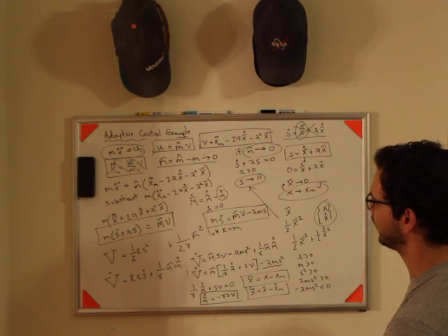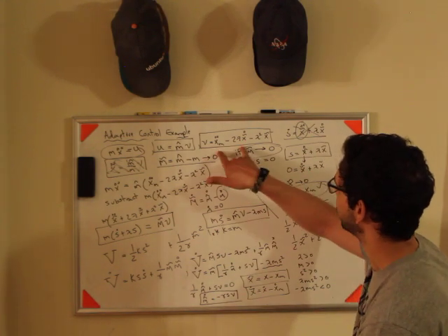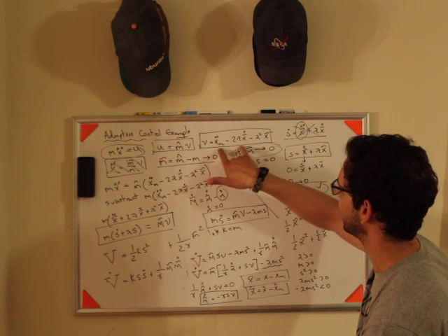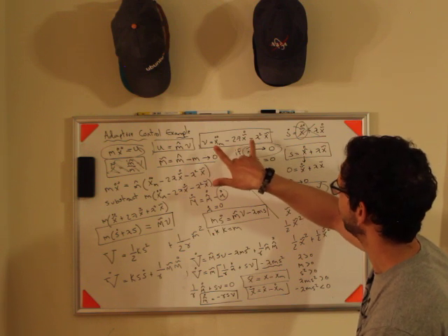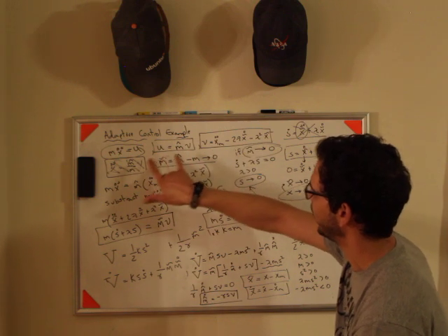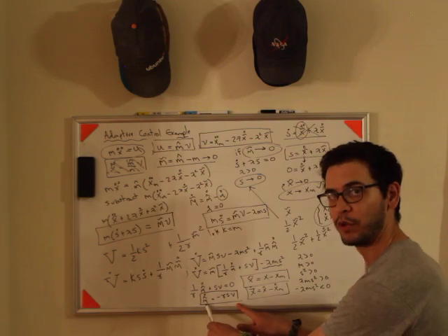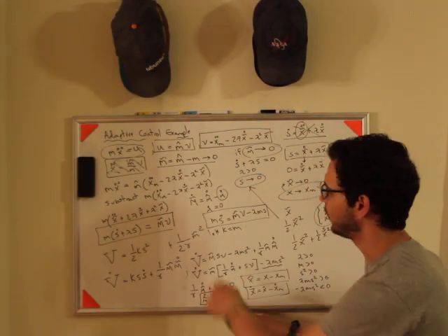So where are your model reference dynamics? I think that was on a board before. If you rewind, you have your model reference dynamics to get x model. You have your pseudo control law. You have your actual control law. You have your dynamics that get hit by your control law, and then you have an update rule for your mass dynamics. So you have everything you need to simulate this.